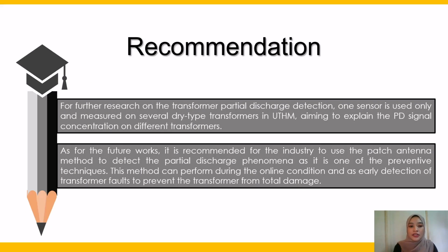Okay, then is recommendation. For further research on transformer partial discharge detection, one sensor is used only and measured on several dry-type transformers in UTHM, aiming to explain the PD signal concentration on different transformers. As for the future works, it is recommended for the industry to use the patch antenna method to detect partial discharge phenomena, as it is one of the preventive techniques. This method can be performed during online condition and as early detection of transformer fault to prevent the transformer from